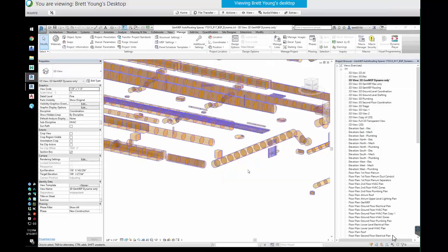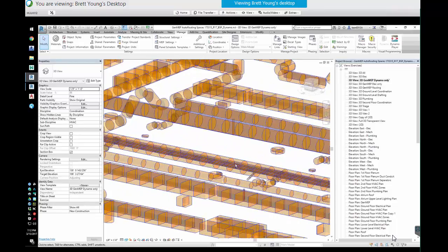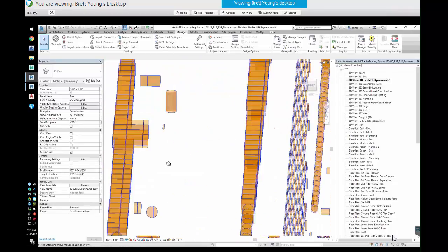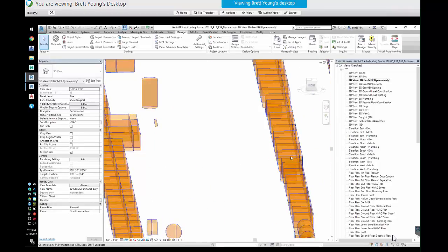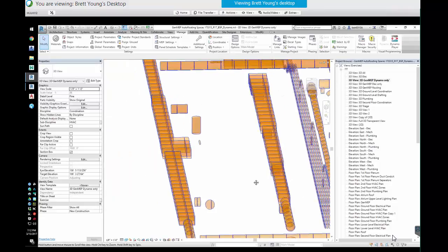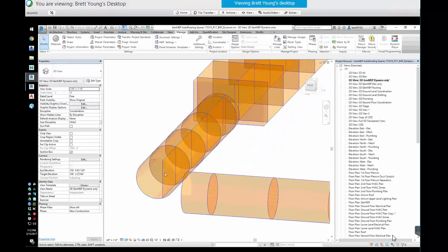Those columns get chopped into pieces. So we have ducts and little pieces of conduit and everything else in between, broken into 1 foot by 1 foot cuts from the top. Where we take that is add up the volume on a column by column basis and divide it by the total volume of the column, which gives a complexity score. So if we're looking in this bottom left corner, this round duct looks like it's intersecting with 2 different plenum columns, so you can see it's cut in the right third.